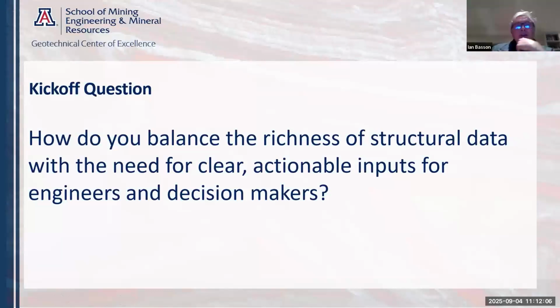Yeah, if I can add to that, I would say in a more general sense, firstly, to try and characterize in terms that the engineers and decision makers can understand a feature, a structure, a domain, etc. Secondly, to build that in 3D space with enough supporting data. Thirdly, to try and find where there may be variations or step changes or changes in orientation of a particular feature, foliation or bedding, which will then guide you towards where your geotechnical domains might be.